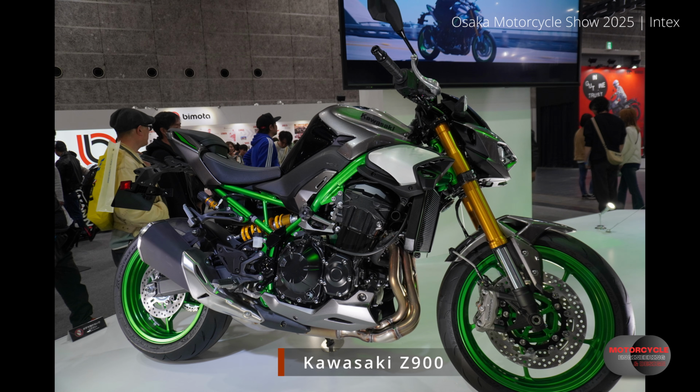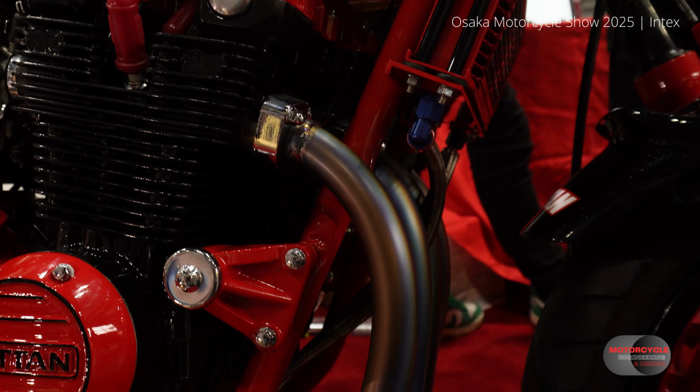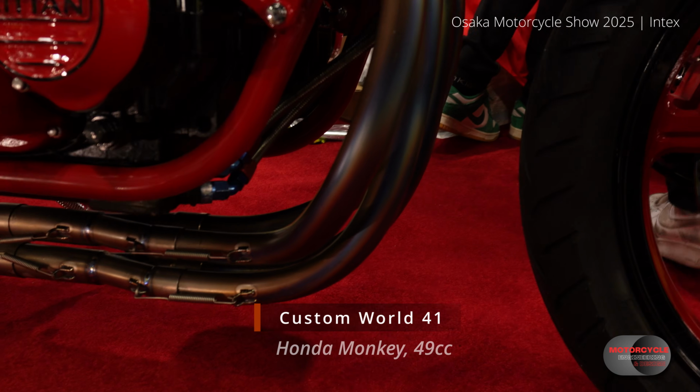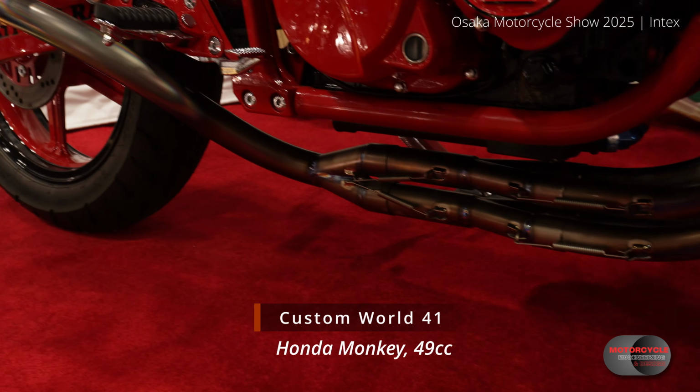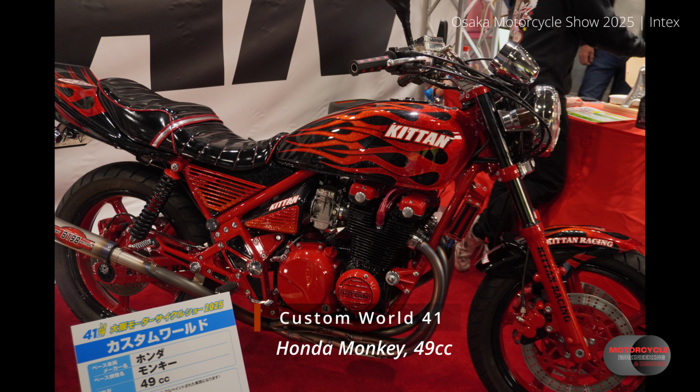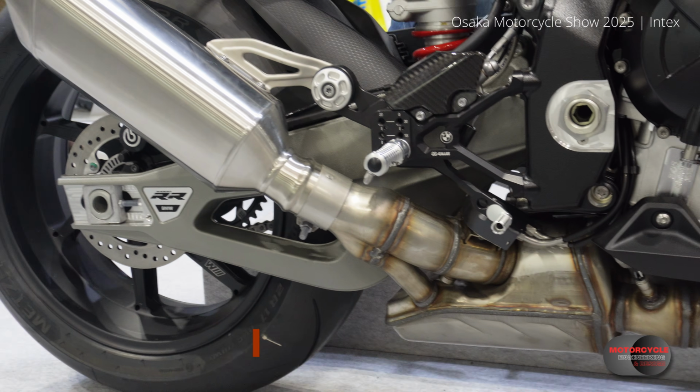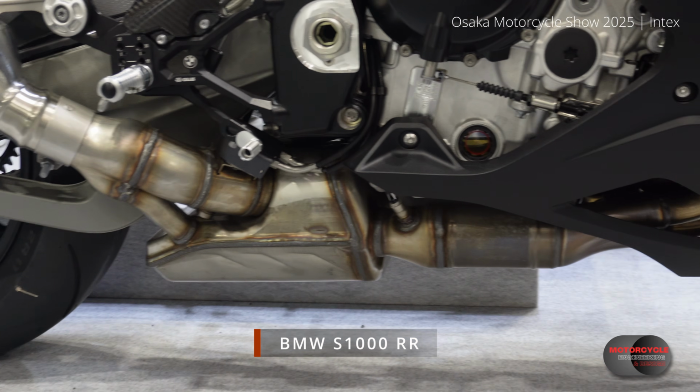Now we're going to need to talk about fluid dynamics. For any flow to occur, we require a positive pressure differential from upstream to downstream. As the fluid flows downstream, we're going to have an amount of friction loss. Essentially, we are losing pressure as a result of friction. Now if this friction loss is so high that we have no pressure differential, then we will have no flow.